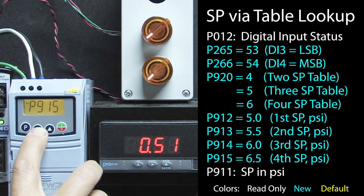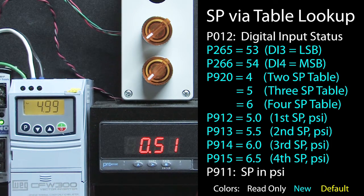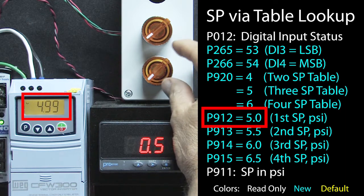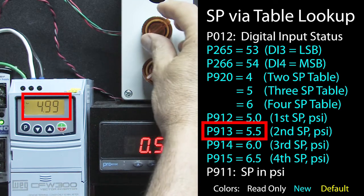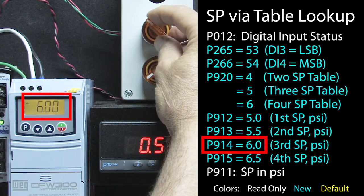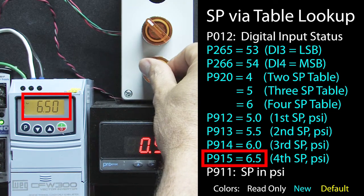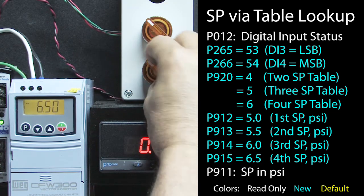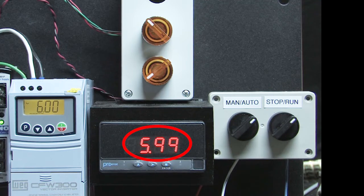Okay, let's go back to parameter 911 where we can see the set point value. Both switches are off, and sure enough, we get the 5 psi we put in that first table entry. Turn on digital input 3, and we get the second value in the table. Turn that off and turn on digital input 4, and we get the third value in the table. And turn them all on, and we get the last value in the table. Perfect. Well, let's go back to 6 psi and switch to run. And of course, the PID application takes the system to 6 psi.